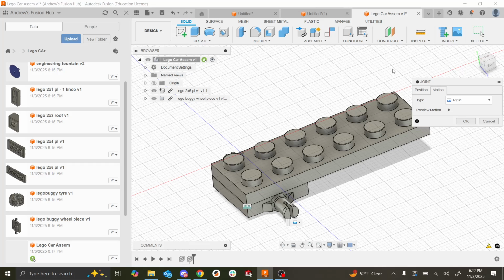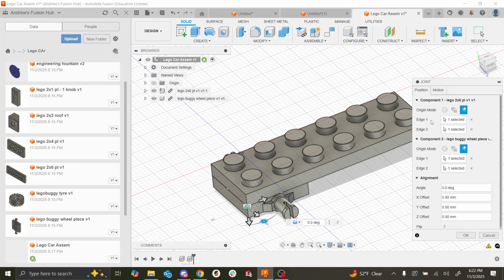And when I say edge-based, when we went to select parts on the components, we selected these edges of the parts, right? And when you're designing things, your edges will change a lot, especially when it's not finished. You might make your assembly file before you finish your design.